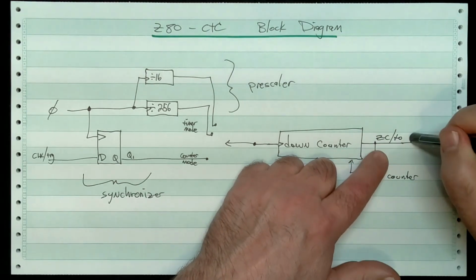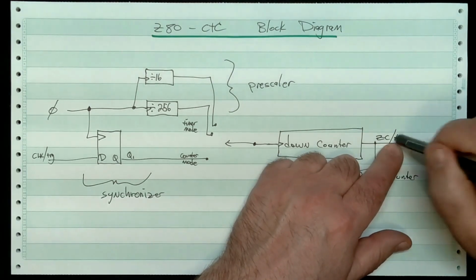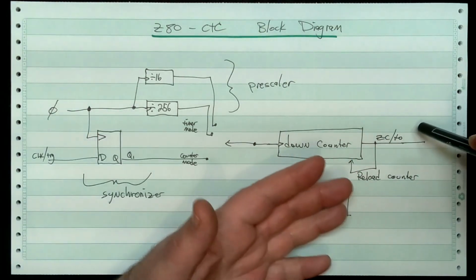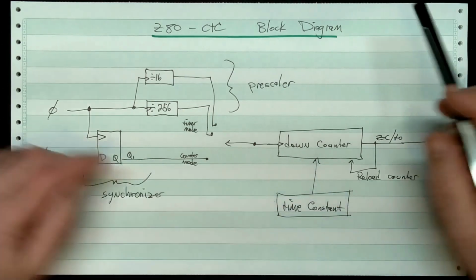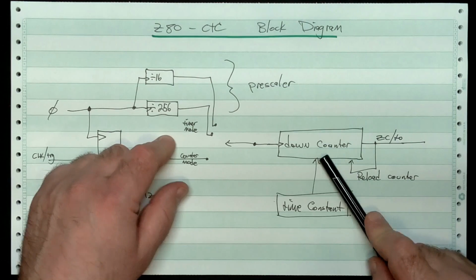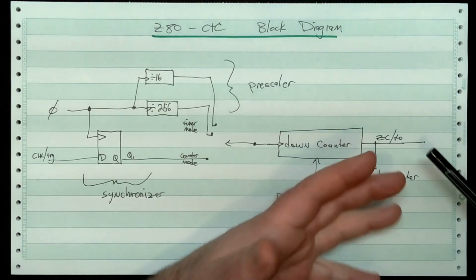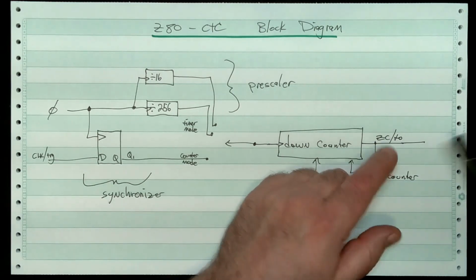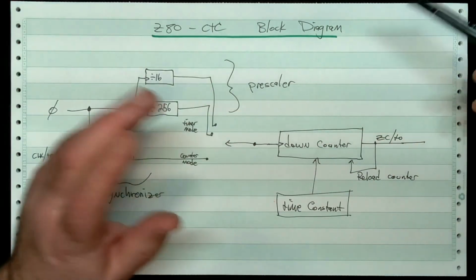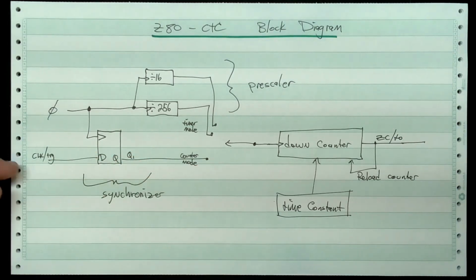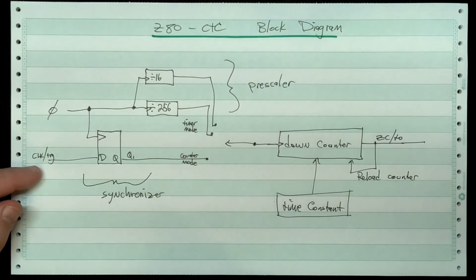So we're going to need to have 9600 times 16 coming out over here. All right. Now, you can't get that evenly. If you have 10 megahertz going in here and you divide it by either 16 or 256 divided by some other value, you cannot get 9600 times 16 to come out of here. It's going to be plus or minus some massive amount of error. So that's why I have another clock that runs at 1.84 some odd megahertz that comes in over here.